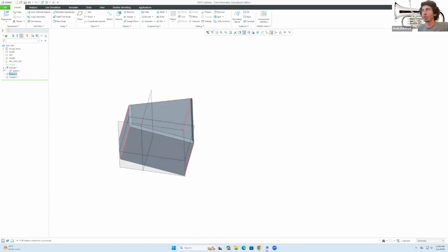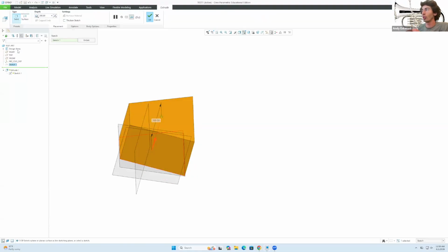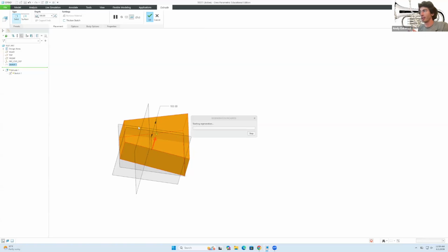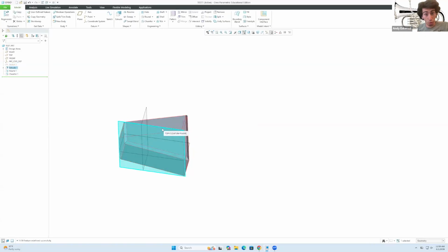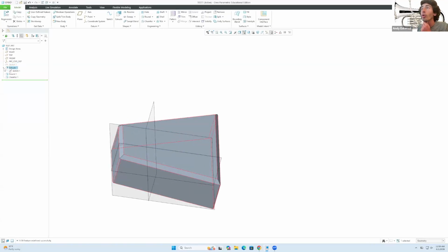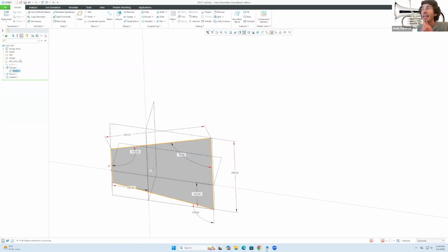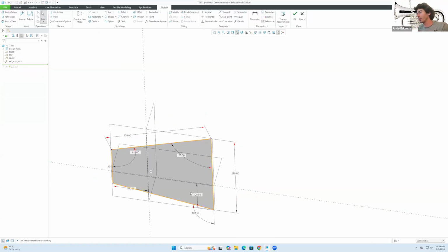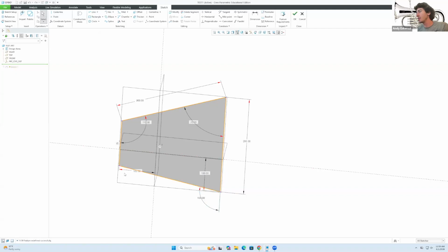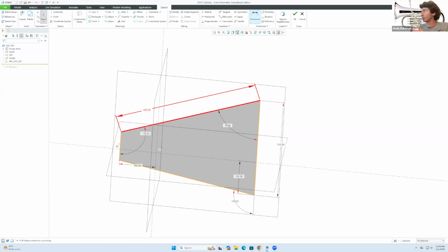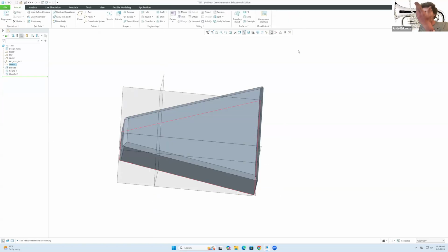And you can also do the same thing about your original sketch. I can go here to extrude one. And well, actually, one last thing. I'll go here and you can also edit your height. For instance, that could have been 100 as an example, and it would accordingly modify itself. Or even better, I can go to sketch one and edit that sketch. So for instance, what if, let's see, a fun one, what if that was 400? So now the shape looks like that. I'm gonna click on OK. Voila, it just regenerates all of it.